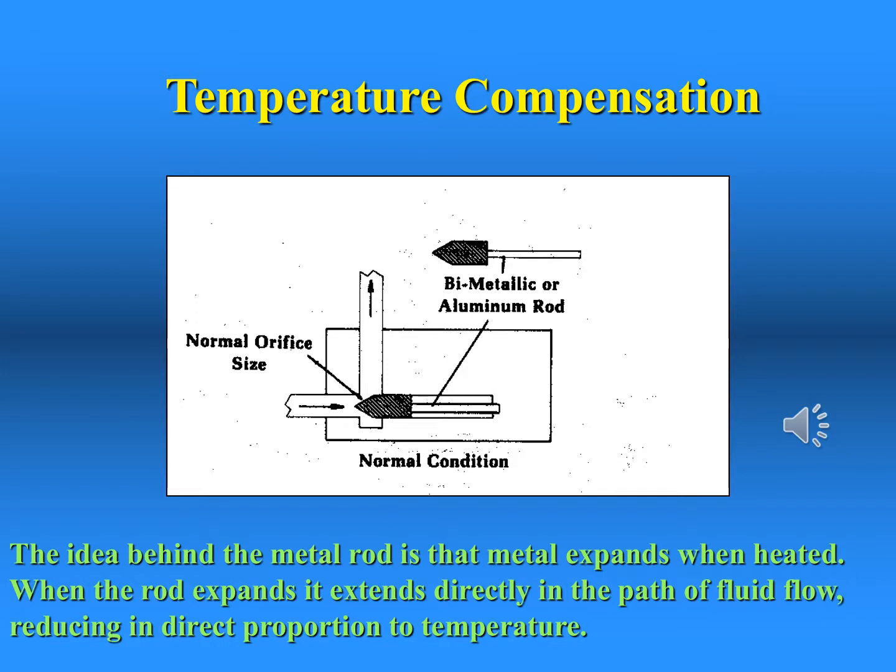There are two types of temperature compensated flow control valves. This one uses an aluminum needle valve which contracts when cold and expands when hot. If the oil is thick because it is cold, the needle valve retracts and this allows more oil to go through. Likewise, if the oil becomes hot, which means it thins out, the needle valve expands and restricts the oil passage. In this way, a valve of this type prevents a speed change in machine operation caused by an increase of temperature.